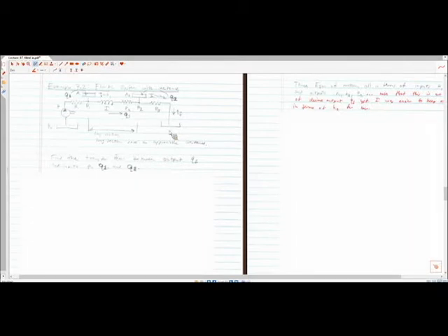So we have resistance associated with this length of pipe here given by R1. The distance between tank 1 and tank 2 is said to be really long. And so it's going to have a certain inertance to it, in that the flow has a lot of mass, therefore inertance. And then we have resistance flowing out, and then we have tanks that we're filling up. And these tanks have state variables of what is the height of those tanks. And so what we want to do is find the transfer function